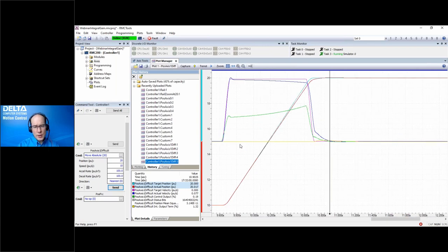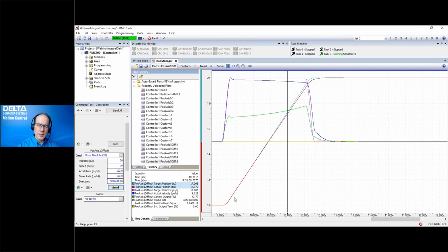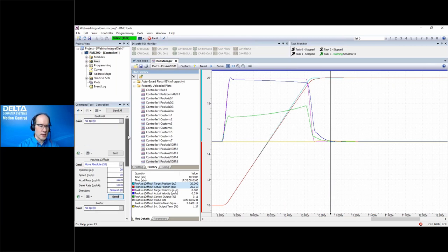An important thing to know is that if you turn off the integral gain during the move, the position won't track as well during the move. So if you need good tracking during the move, this is not a good option to choose. But if you're basically just setting a set point you need to move to without overshooting, this option of setting the integrator mode to TG done is a good option.